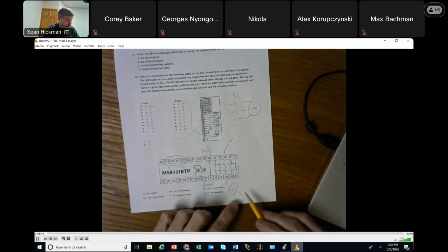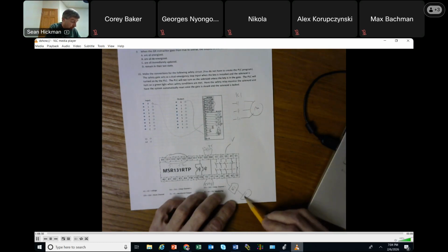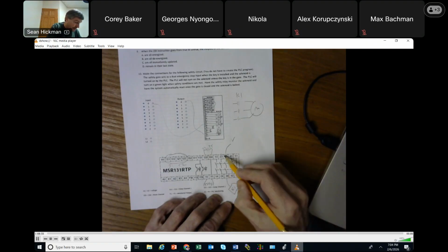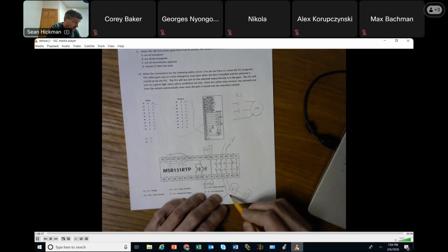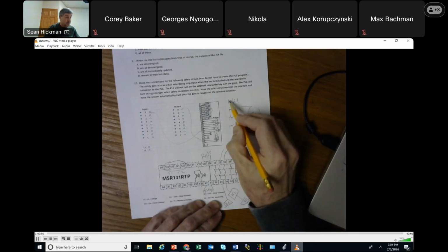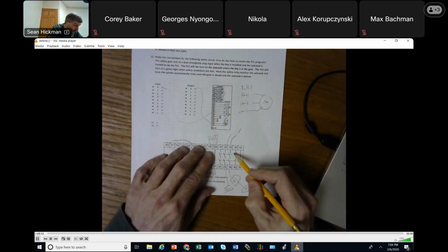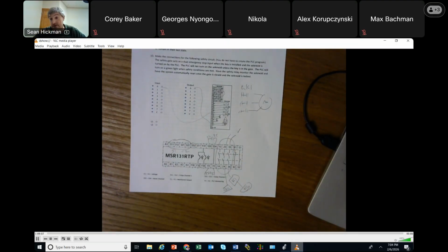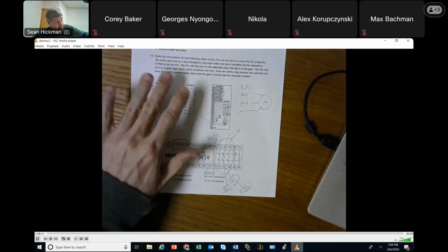If you want to be doubly redundant, I'm sorry, you could have turned on another one in parallel, or you could have passed the voltage here for K2 and put in another set of contacts here, K2. So once again, these are the big contacts that have nothing to do with any of this. These are doing all the hard work.